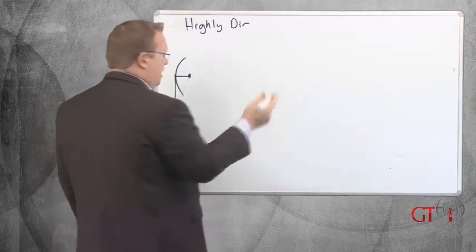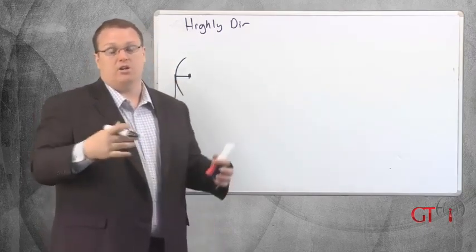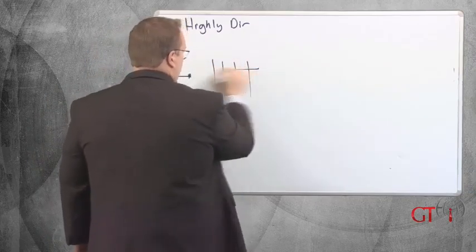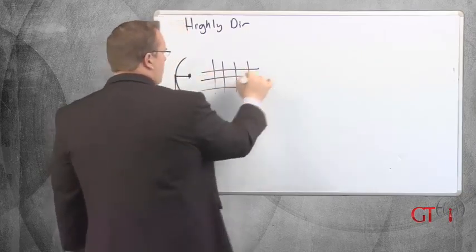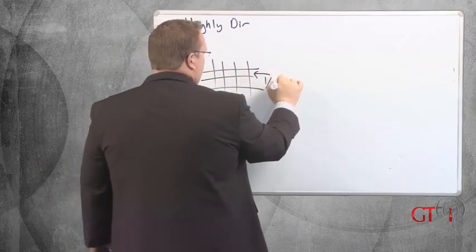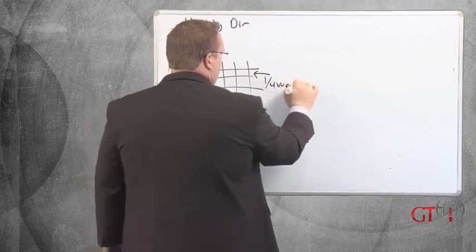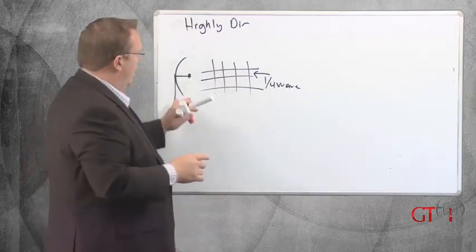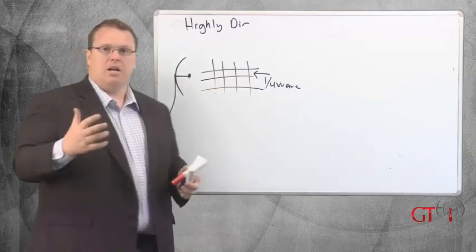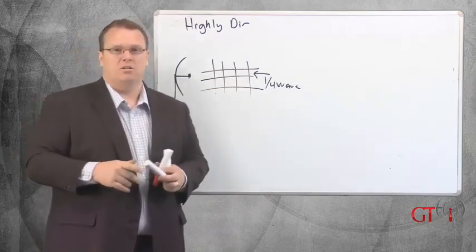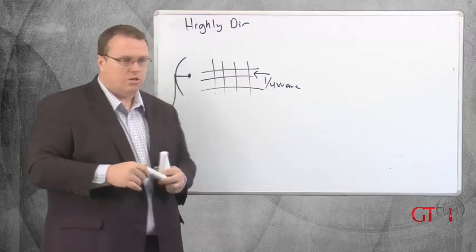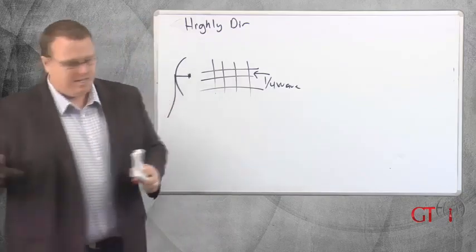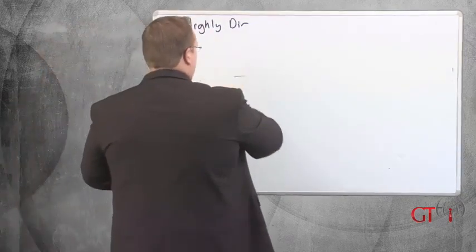A grid antenna looks kind of like a barbecue. In fact, if you're a super Wi-Fi geek, you could actually use it for one. It's curved, and it has these hash marks. It's basically built just like you can imagine a barbecue. By the way, these are all in 1/4 wavelength of the frequency that antenna was designed for. So this grid or dish, now the grid upside is it doesn't get affected by the wind as much. It's really super cheap to produce, very inexpensive. The beam pattern that you'll see can be very, very tight.